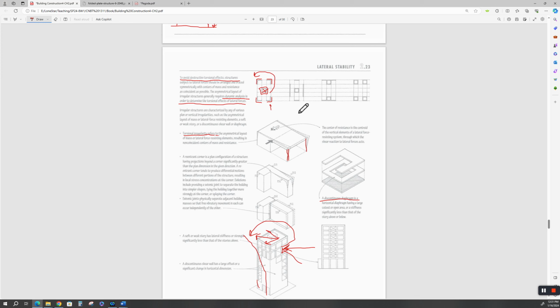Here's intermittent shear walls. You've got some long ones down the long axis of the building, and you've got some short end ones, and still we have this center column. A lot of your super high-rise buildings will always have a center core. That's what this box represents. Down through here would be a center reinforced concrete core.